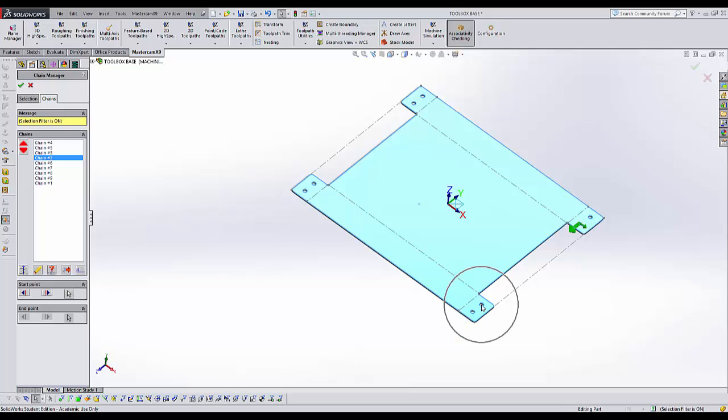Now we want to get to this one here, which should be after two, which that one we know can move down. That would probably be at the bottom. That one will be right after 7. And then this one needs to move down 1. If we look at it now, we should have it organized. First toolpath, second toolpath, third toolpath, fourth toolpath, 5, 6, 7, 8, and then profile. Not a lot of movement there, but it worked great. I'll hit check.